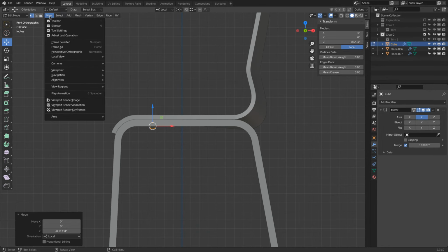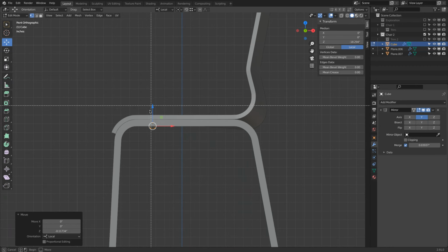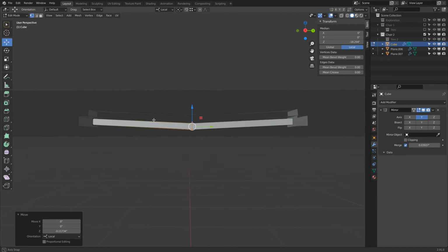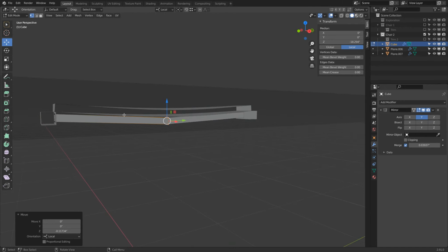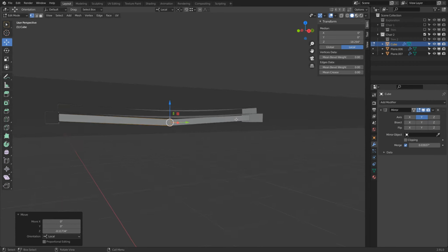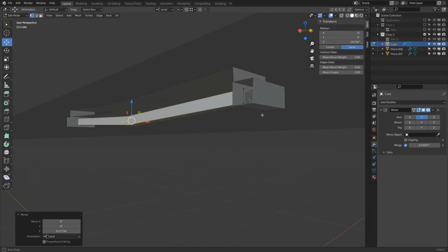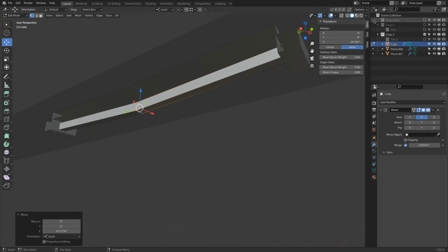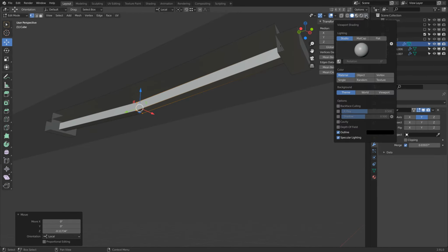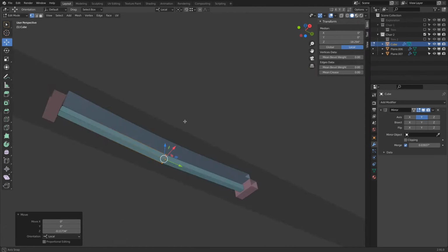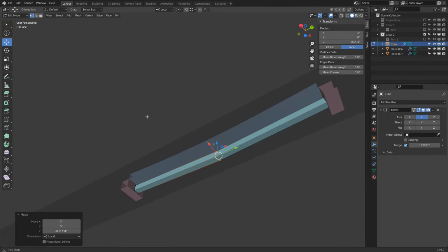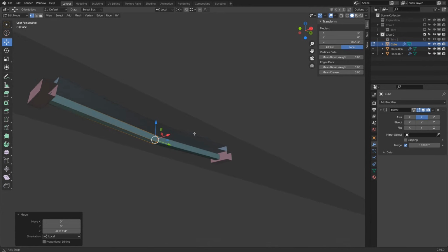We know that in view and view region, clipping region, I can do a clipping of that geometry. Now I can see how this pipe relates to the top part. Also, because of the color, everything being gray, this is difficult to read. Let's go to here, viewport shading, and turn on random color. That's a lot easier now to read. Okay, very good.